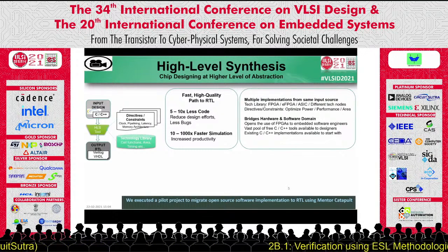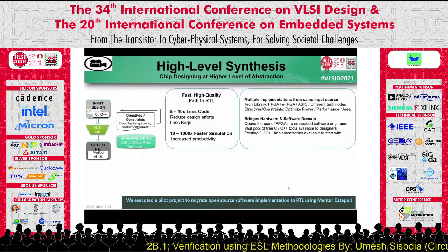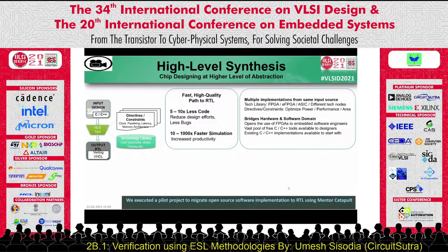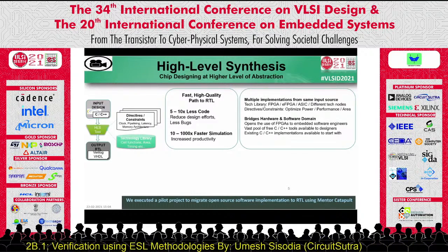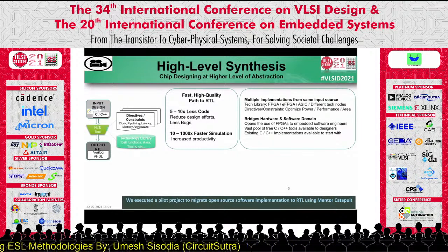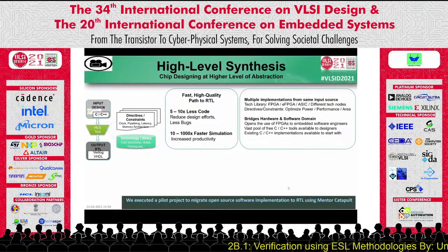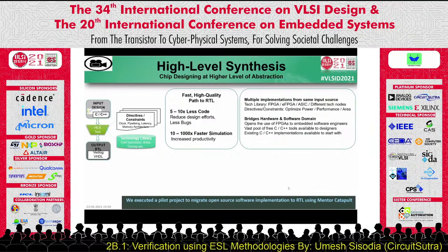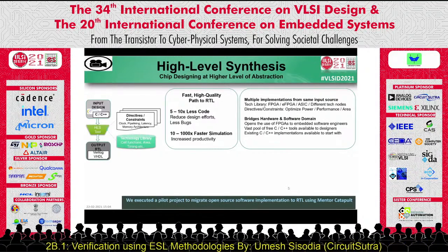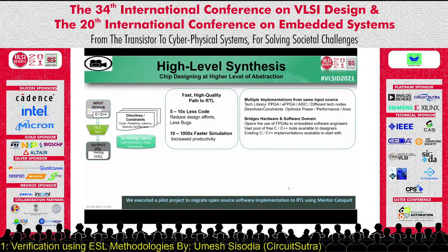With the same input design, we can generate multiple implementations of the RTL for different technology nodes, different technology libraries, or different application areas requiring different levels of optimization of power, performance, area, etc. HLS bridges the hardware and software domains, and it makes the vast pool of C and C++ tools available to chip designers. Moreover, we can use the existing C and C++ implementation as the starting point for our chips.